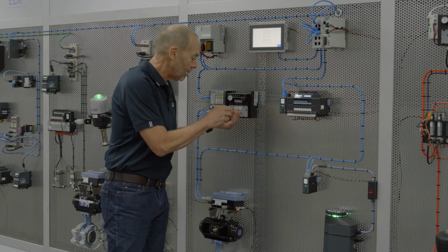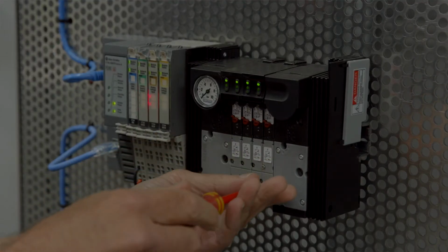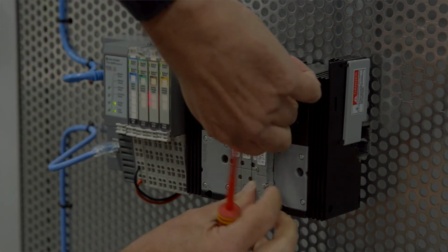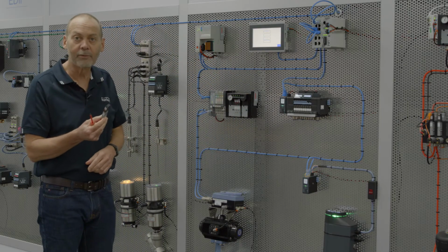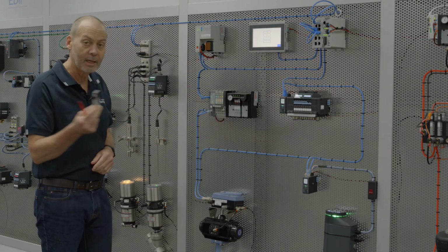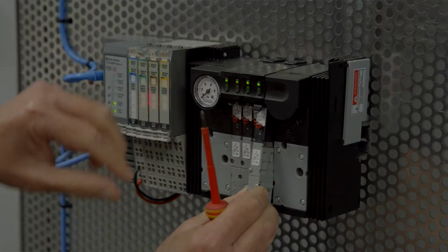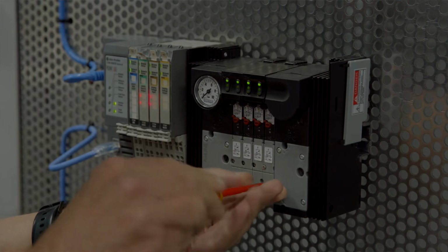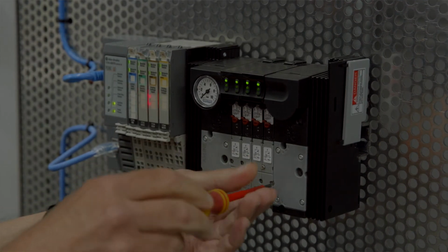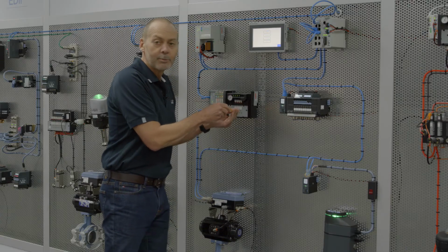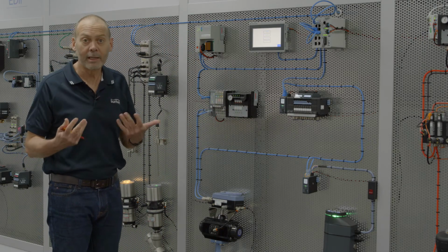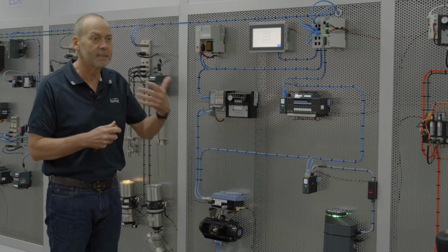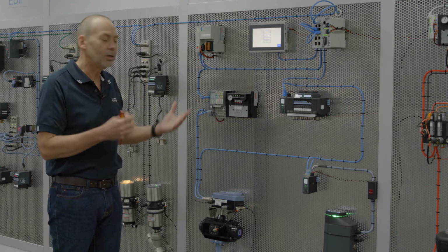We have the option of having a full hot swap capability to swap out valves under full operational, so full air and full electrical connection. And of course, you can replace the valve and get back up and running in a very quick period of time. We do this as Bürkert is designed to run in the process automation industry. And in process automation, you have things like fermenters and distillation, etc. You can't turn those processes off.